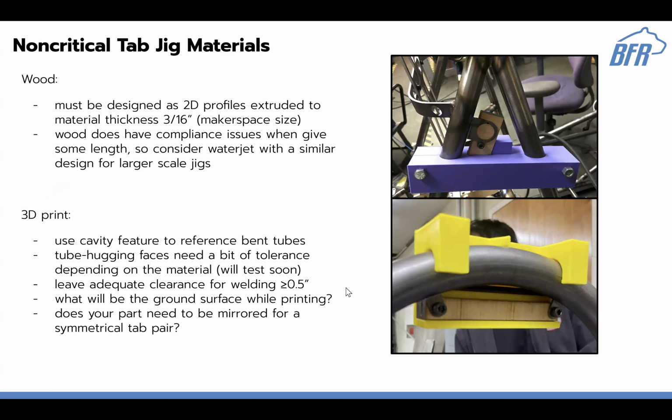Some other stuff with 3D printing: it's important to recognize what orientation you're actually using for your print vector. When the printer is laying down filament, it's very accurate in the 2D plane, especially when drawing outlines and circular shapes. But when it's stacking layers, there's a certain amount of resolution you might run into with different print layer thicknesses.